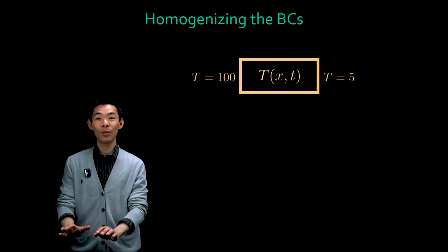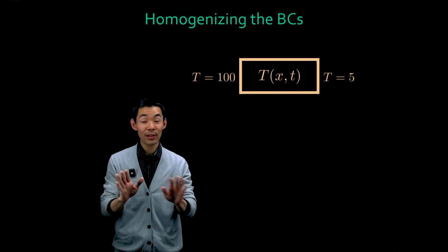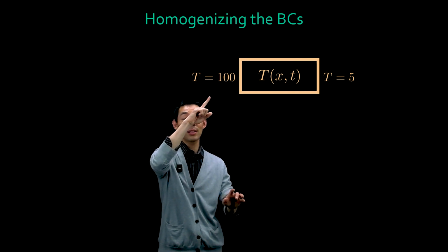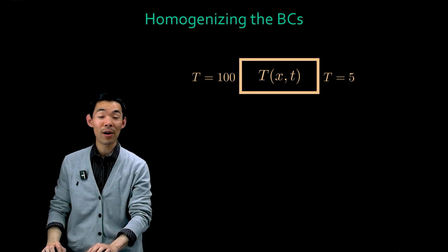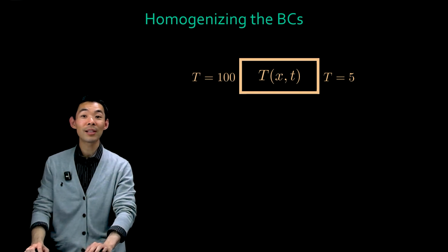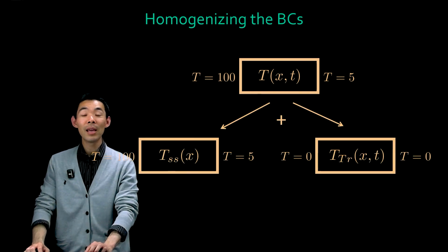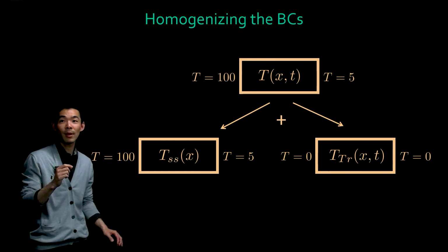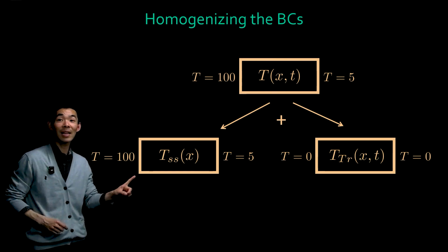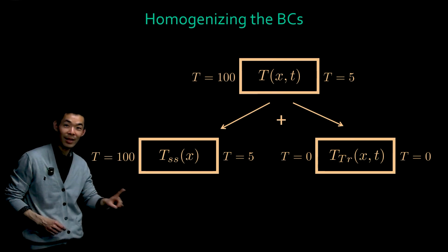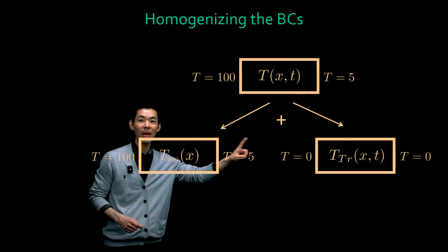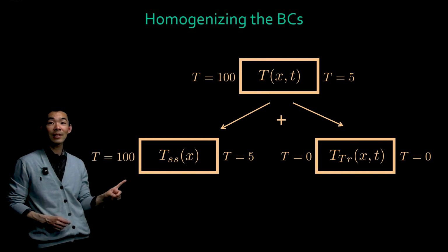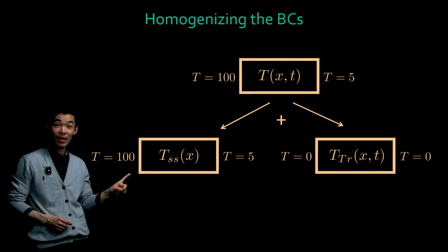Let's review, once again, the problem we did earlier. Forget about the insulated boundary condition, just constant temperature, where you know the function value at both boundaries. Now, we have non-homogeneous boundaries at both ends, and we have to split it into two problems. One problem is the steady state solution, where you put your non-homogeneous boundary conditions on both the left and the right, and you solve your purely steady state heat transfer problem.